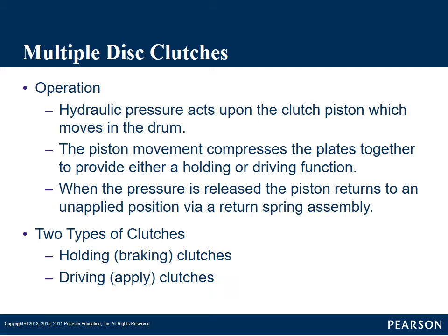That locks that drum, because remember, our steel plates are lugged or splined into the drum, and our friction material is splined onto a gear or another drum. So when we lock that clutch pack together, we are then taking that drum and locking it to another drum, to a gear, and that directs the power flow. When we do that, that's when we get another shift, depending on which clutch pack